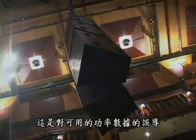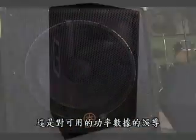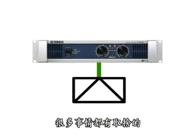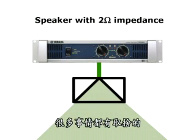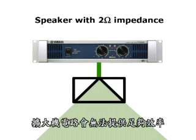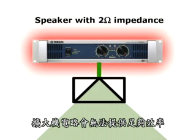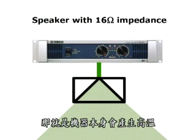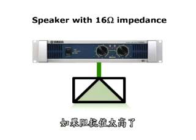So why not have all loudspeakers running at super low impedances? As with most things in life, there is a balance. If the loudspeakers have impedance ratings that are too low, the amplifier might not be able to effectively power the system without generating too much of its number one enemy, heat. And if the impedance is too high, the path the signal flows through will be too restricted.